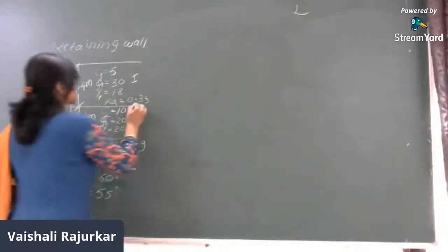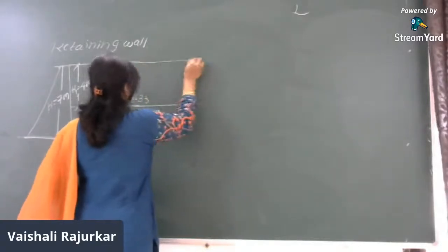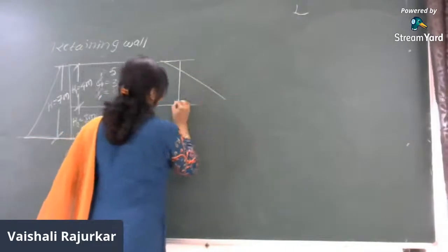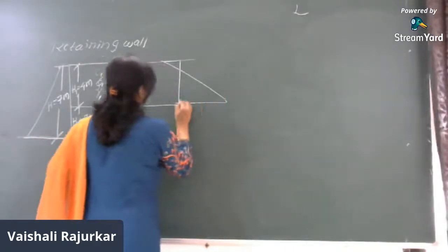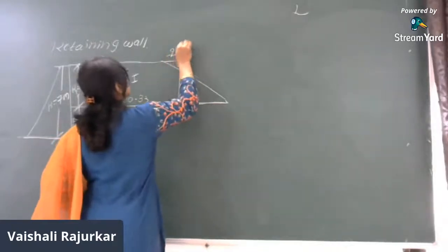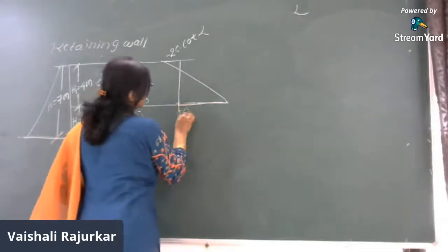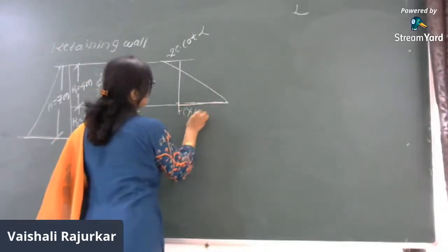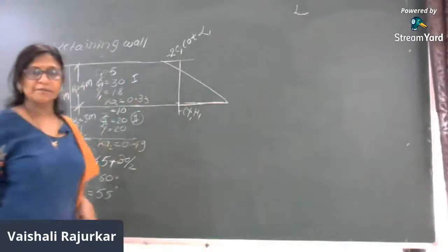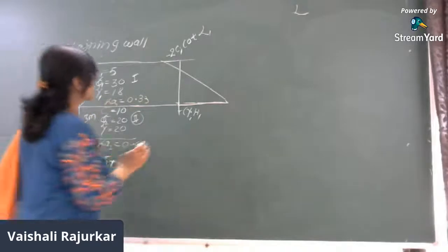So in this case, this is the simple case of the cohesive backfill. Here the diagram is a negative-positive diagram. So this is the diagram. Here it is minus 2c cot alpha. It will be over here gamma 1 h1, c1, alpha 1, right? So all the parameters which are related to the first layer will be taken into consideration.